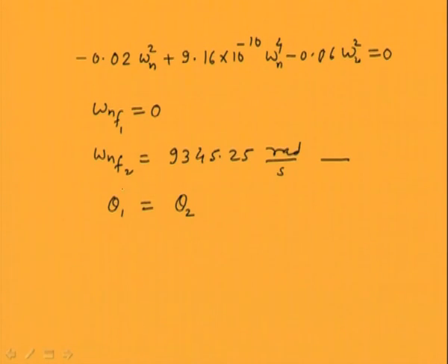That is, this is in more explicit form, this form, okay. And other intermediate displacements also can be checked through the transfer matrix method, in between transfer matrices, and you will see that all the displacements will be having same value, because corresponding to the 0 natural frequency we will be having all the displacement equal, that is rigid body mode.